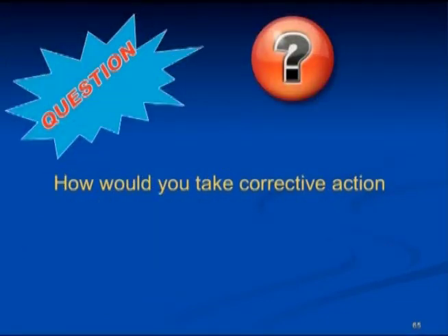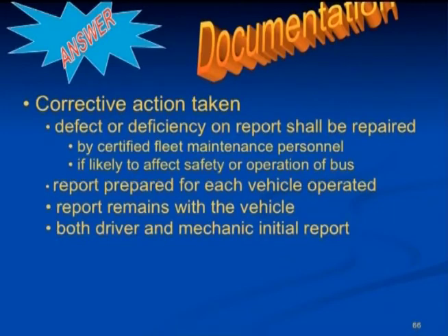How would you take corrective action? The defect or deficiency on the report shall be repaired by certified fleet maintenance personnel if it is likely to affect the safe operation of the bus. A report is prepared for each vehicle operated. The report remains with the vehicle, and both the driver and mechanic should initial the report when a repair is made.